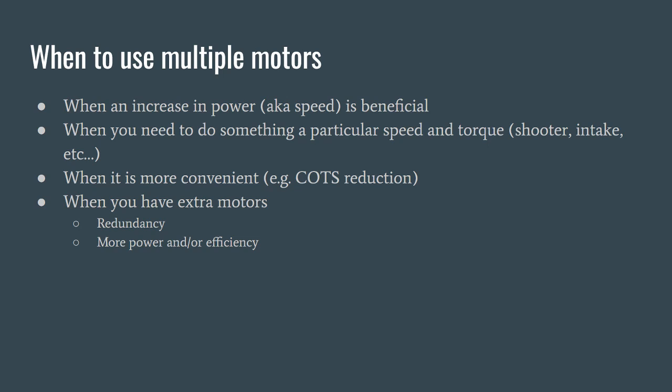Sometimes you might also want to change the number of motors because you can't get a reduction really easily. You're like, well, if we add a motor, we can just throw it in an off-the-shelf gearbox and it gives us the right stall torque. Right? Because if you have more motors, you have a higher torque and you need less of a reduction. Does that make sense?